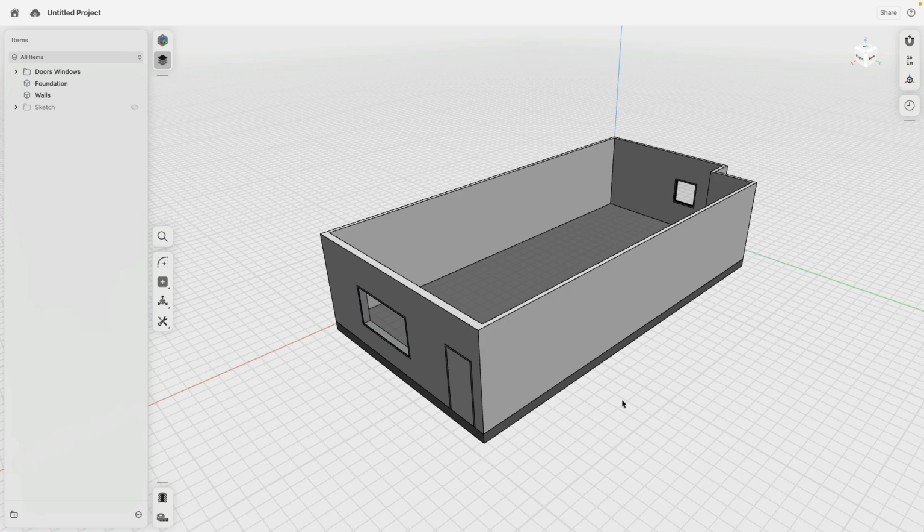Whenever you work with an architectural space, or actually also an object, piece of furniture or something, and you would like to look into the space, you want to open it. One very easy way is to use the section tool. We have this lower left corner here in Shaper 3D. When you click on it, you start the section view.